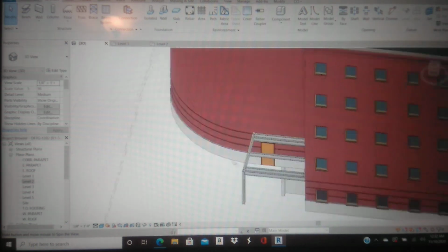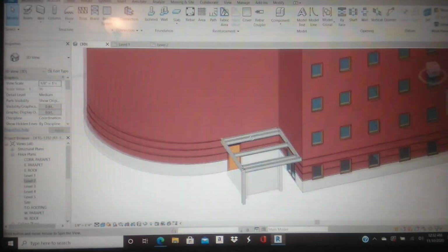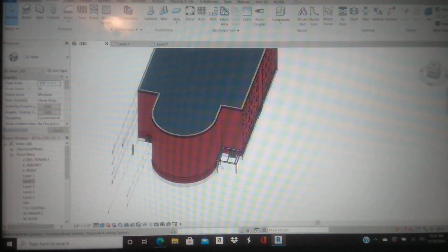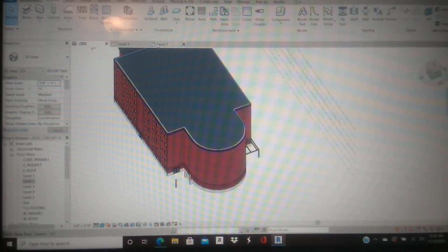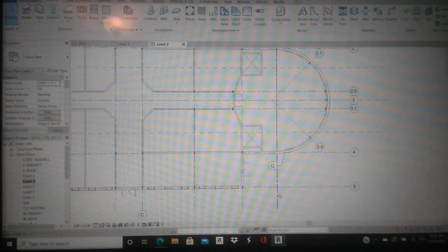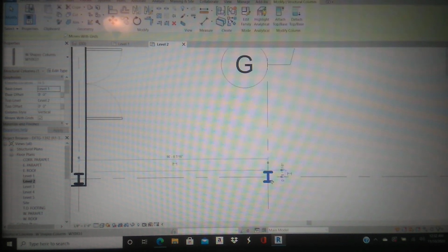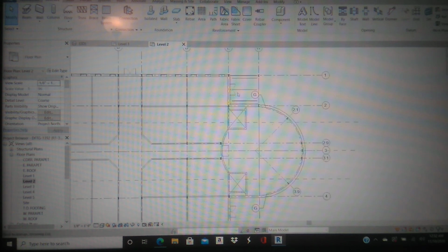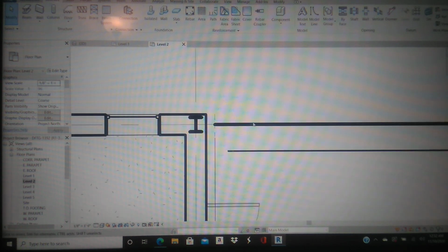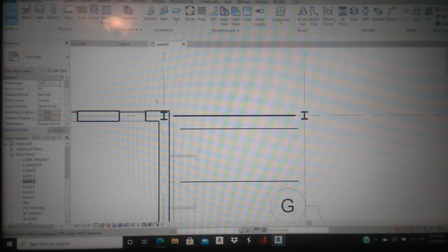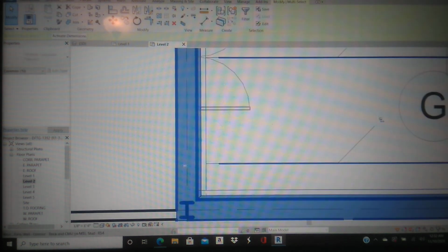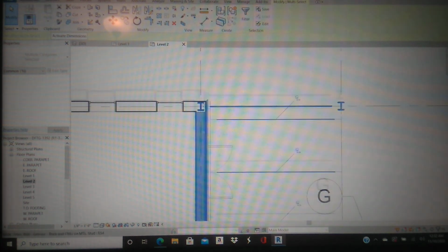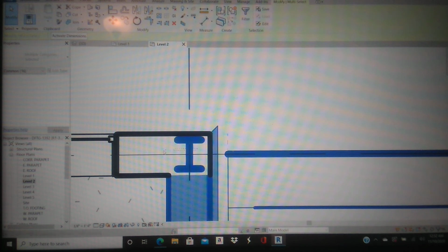All right. So I know it still doesn't make a whole lot of sense, but we're kind of framing up the building at this point. So what you do want to do is go back to level 2, okay? And let's go ahead and take this guy out. Let's delete that. And what you want to do is take this entire beam system, okay? With the exception of the walls, you have to unhighlight some things. Let's see how we can do that quickly. We don't want this guy.